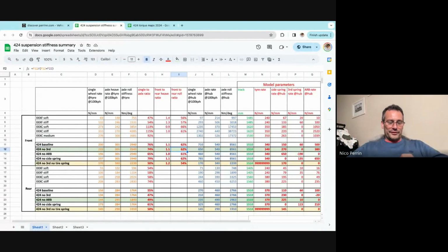Remember the weight was 47, aerodynamics was 45. They were more towards the rear. Now I'm saying the stiffness is more towards the front. And again, the reason is because by having a stiffer front suspension, you're allowing the rear to be a bit more free, and that will give you more grip. So again, you're actually favoring grip at the rear. And this is again for stability. This is because we have more load at the rear. We've got more power going through the rear wheels.